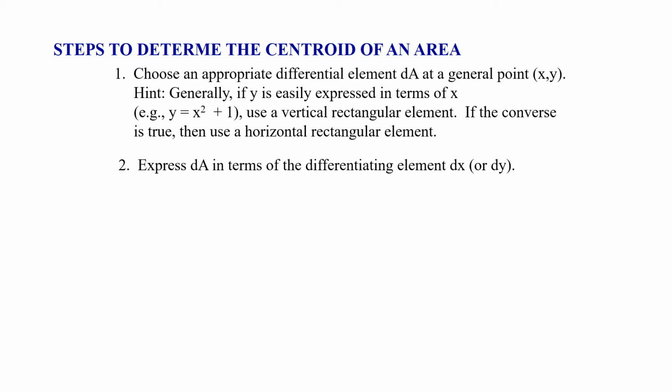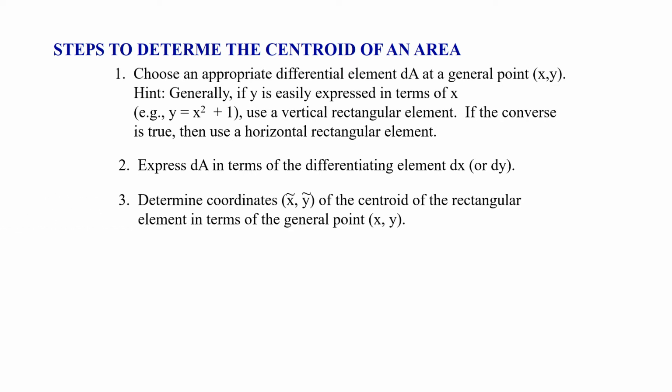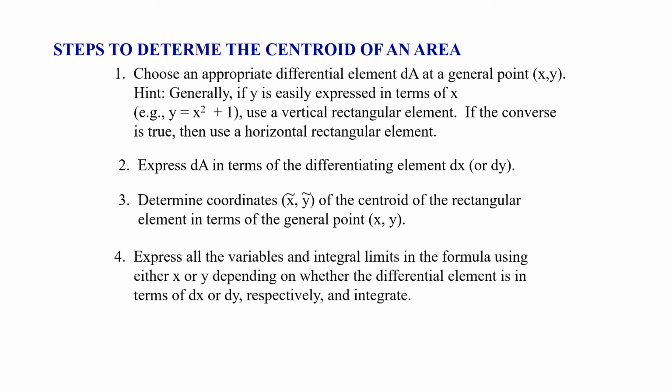Next, we need to express dA in terms of the differential elements dx or dy. Third, we need to determine the coordinates x tilde, y tilde of the centroid of the rectangular differential element in terms of the general point x and y, and then express all the variables and integral limits of the formula using either x or y, depending on whether the differential element is in terms of dx or dy, respectively, and then we need to complete the integration.